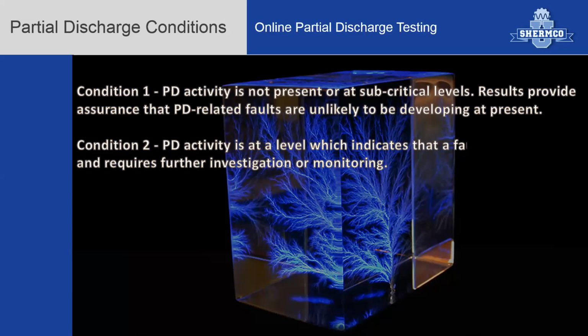Does the partial discharge seem to kick in when load cycles go up and then dissipate when load cycles go down? Possibly it's triggered by thermal, maybe weather conditions and so forth. Heaters inside the switchgear cabinets maybe are at fault and are actually the root cause of the problem. So during very hot, humid days, moisture content builds and we're in a condition 2, partial discharge showing evidence of possible corona or tracking activity.